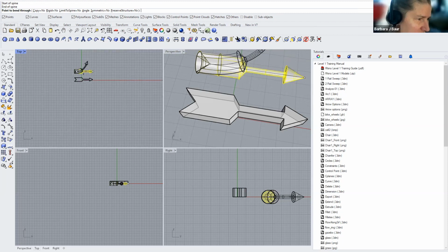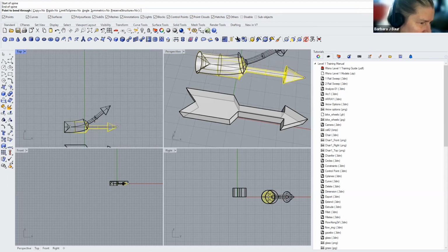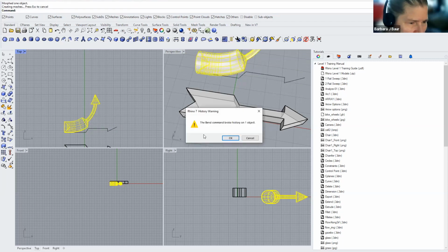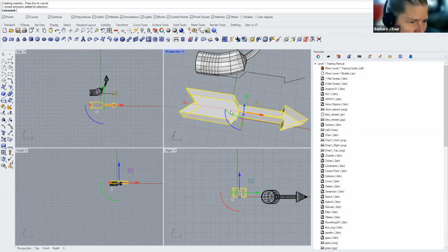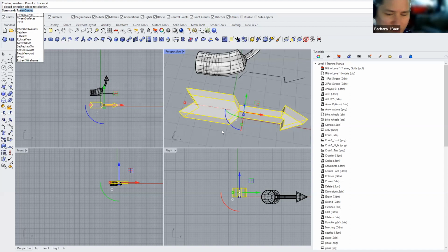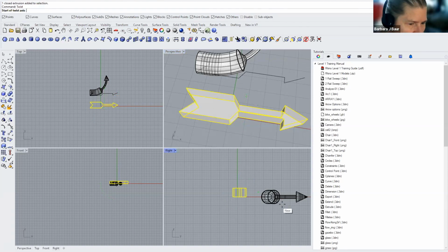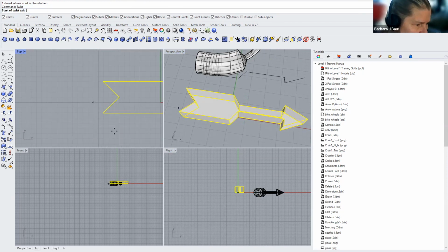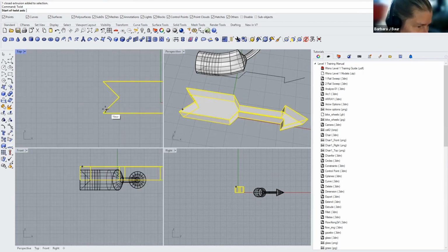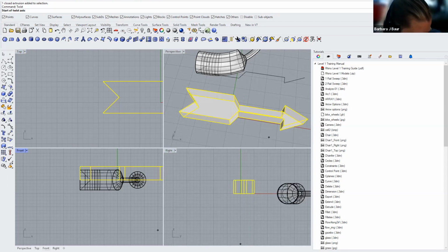I'm just going to zoom out a little bit. Zoom in this way. We're just going to go like, okay. That's fine. So, how do we twist this guy? We use the twist command, TWIST. And over here, I want to twist in the very center of this. So I'm going to make sure my mid snap command is on.